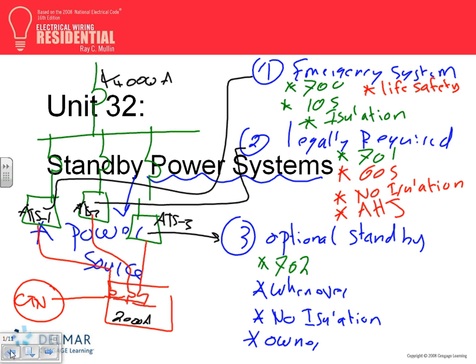The transfer switch is either on normal, completely isolated from the emergency system, the generator, or on generator, completely isolated from the power source. What does it do when it shuts down? Does it recognize power coming in? Yeah, very good point. The auto transfer switch has a brain, guys. There's electronics in it.